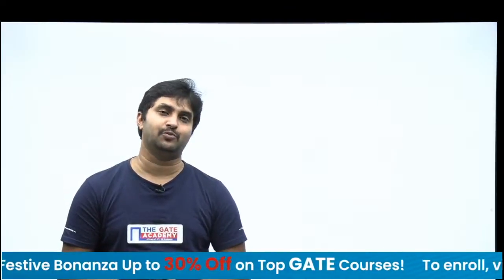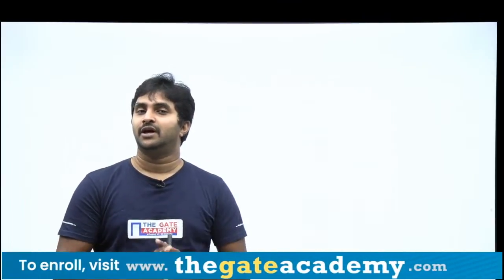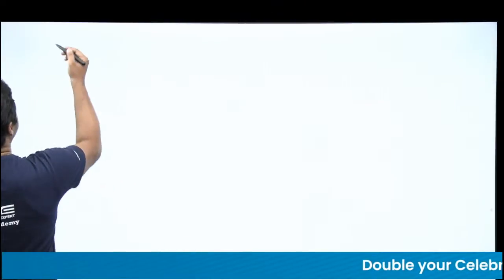It is not possible to build a non-causal system if you are having a live input. If you are having a recorded input, then it is possible to build a non-causal system, because in the case of recorded input, you have access to what is going to come next. Is that clear? So mathematically speaking, let us solve a problem.